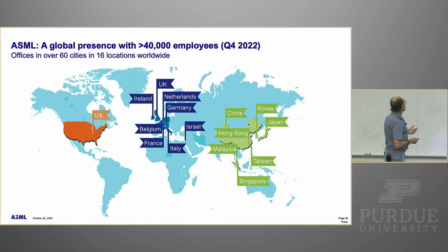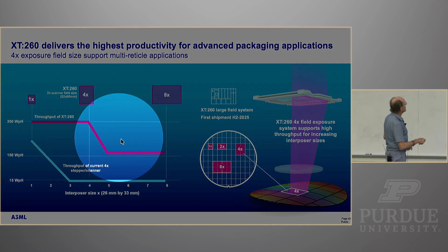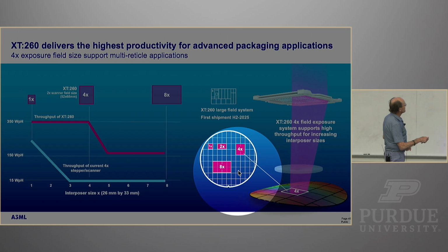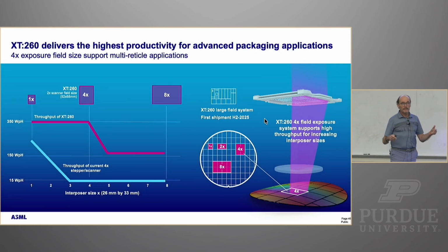So, lots more about this light source that we already talked a little bit about. Packaging. Now that people are going to more advanced packaging, even the substrate where all these packages are put on is becoming complex. Semiconductor technology, these are interposers. We're now launching a series of scanners where we can take very large interposers with semiconductor technology, and that means even more connectivity between memory and logic and more performance.